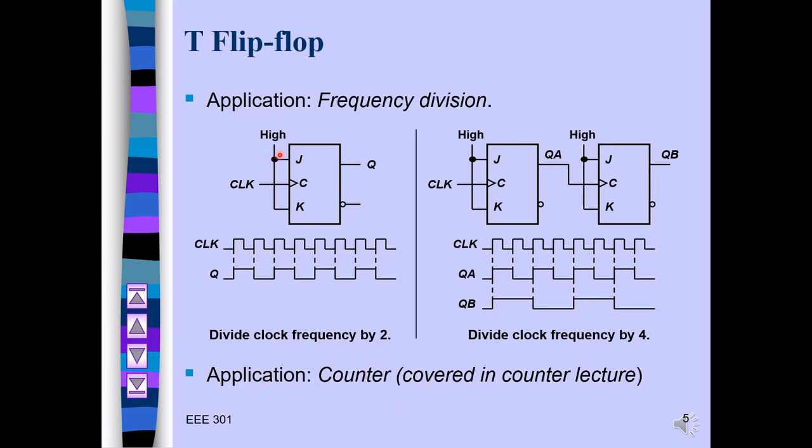If you look at here, this is basically your T flip-flop, because your K is shorted with J, and you have the clock as well. This is obviously the rising edge of the clock. If you look at here, this is your clock. Whenever your T is 0, it will remain as it is. Whenever it is 1, it will be toggling. If previous is 0, then 1; if 1, then 0.